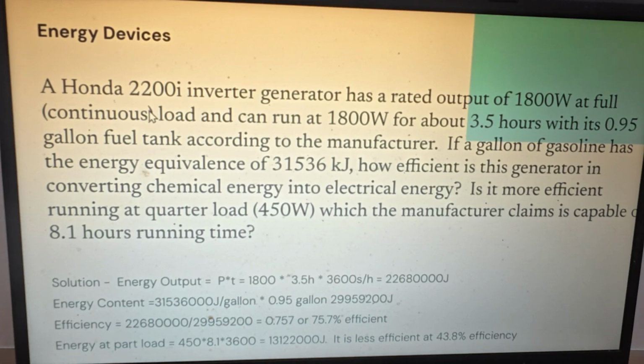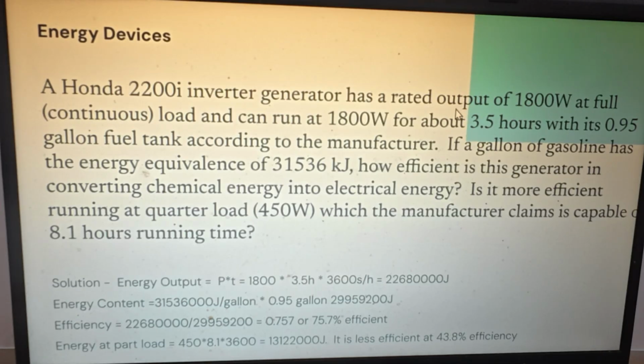There are two kinds of generators out there in the commercial market. There's what's called an inverter generator, and there's another one called a synchronous AC generator, which are your old-fashioned generators from many years ago. Before these inverter generators became popular, all the generators were synchronous single-speed generators, and they only run at one speed, 3,600 RPM in the US, because it has to be a multiple of the 60 hertz grid that we are operating in.